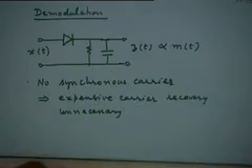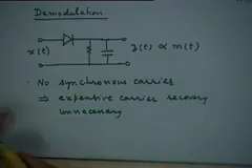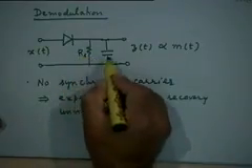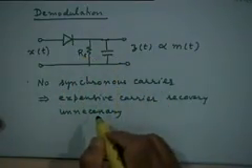If it becomes more than 1, essentially that shape following property will not be there, and we will not be able to have the advantage of using a very simple demodulator. And the demodulator structure was extremely simple. This was a circuit we discussed very briefly. We will discuss it in more detail now, where you have a simple diode followed by a resistor R_L in parallel with a capacitor C.